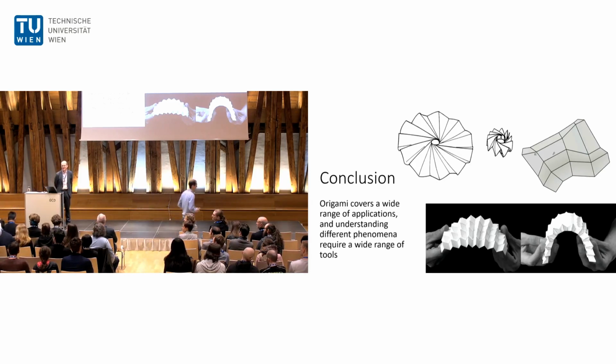Thank you for the interesting presentation. You have mostly spoken about rigid origami, as you said, but you have also underlined the importance of taking flexibility of faces into account. So I'm coming from mechanics, and I'm interested in this part of your simulations. Was it finite elements, plate finite elements, which you used for modeling this flexibility? And if yes, how did you in general ensure the continuity conditions on the edges between those faces?